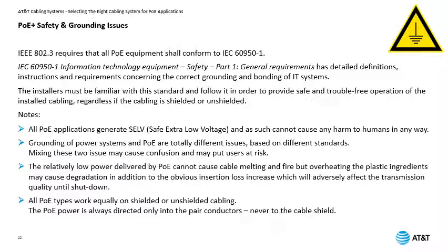The PoE power is always directed only into the pair conductors, never to the cable shield. But always remember, shielded cable is better for heat dissipation. Therefore, if you have many bundles, it is recommended to use shielded cables.